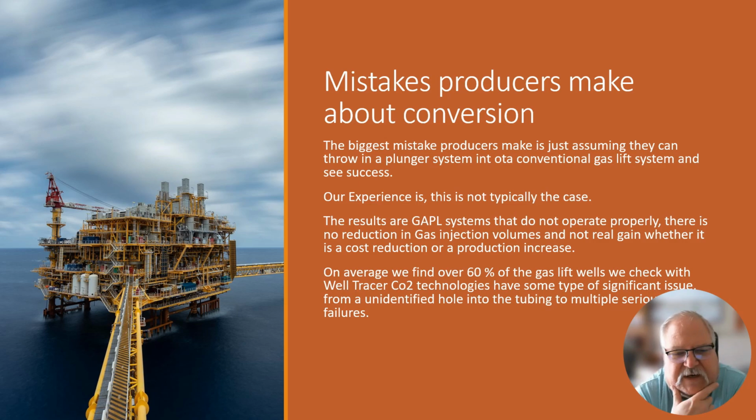On average, we find that probably 60%, probably higher, probably closer to 80% of the wells we check with CO2 well tracer or echo meter, we find pretty significant issues, from unidentified holes in the tubing to multiple serious failures. We do find a lot of plugged orifices in the bottom, especially in the Montney up here, and we see that in the Duvernay a little bit, where we'll actually see the orifices plugged off.